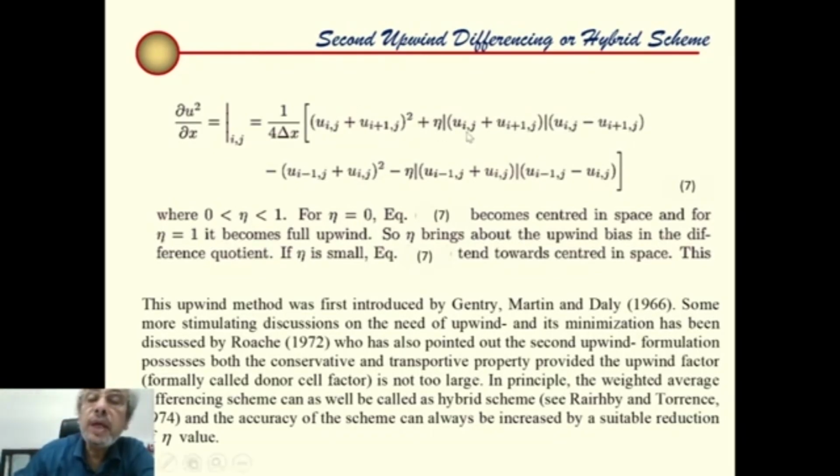So if you do a little exercise on your pen and paper, you will see that to introduce that sort of versatile character, it doesn't matter if you write this way and program this way, locally anywhere velocity may become positive, may become negative because of flow separation, several other things. It will not affect, and it will eventually take the right value, positive or negative, if we introduce modulus sign here.